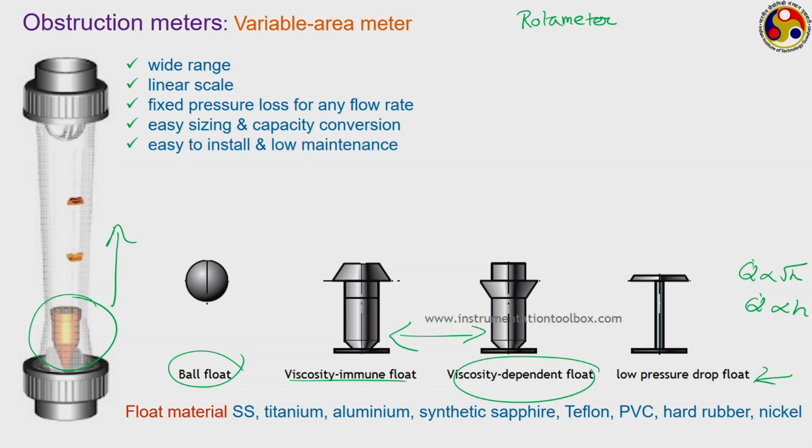Just like in this diagram, the flanges are shown, which in this particular case generally have some kind of threads. They can easily be tightened to the corresponding threads on the main pipeline, and we can start using this immediately. Hardly any calibration required, because they always come pre-calibrated, and we do not have to go for frequent calibration. Very low maintenance requirement as well.